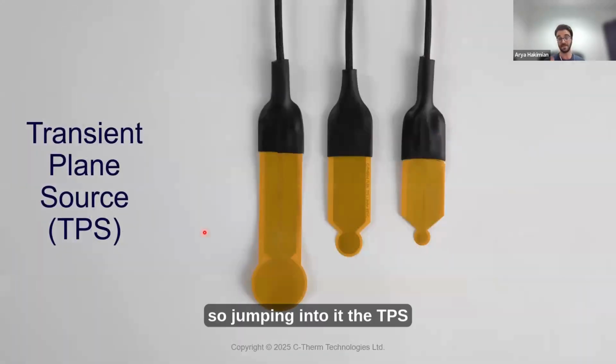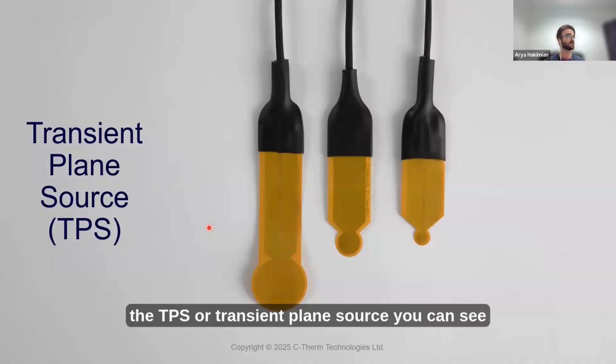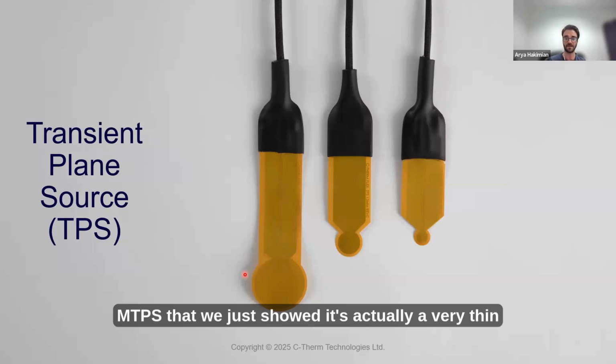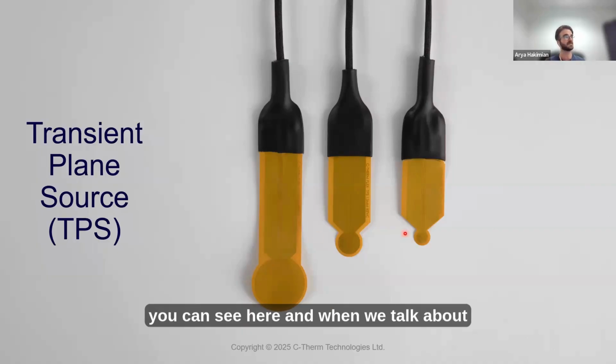So jumping into it, the TPS, like I said, is another method that is available on Trident. The TPS, or transient plane source, you can see the sensor design is very different from the MTPS that we just showed. It's a very thin, flexible, double-sided sensor, available in different sizes, as you can see here.